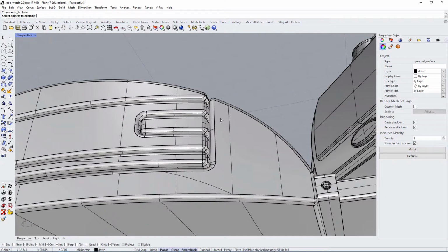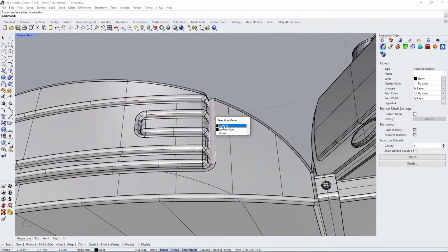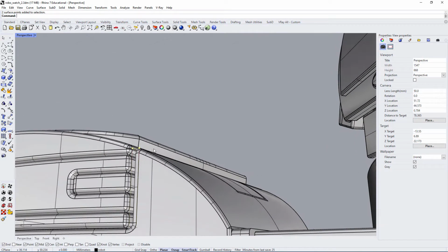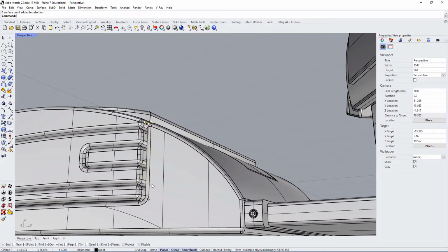so if I explode it, I don't know why it's not letting me explode. Yeah, here it is. And if you look at how it's built, you will see that some of the points of this surface basically tell you how complex that transitional is. And this transitional is made up of 3 points, which tells me that this is actually essentially a cylinder. It's based on a circle being extruded. And this is what makes your fillet. The fillet is usually a radii, right?